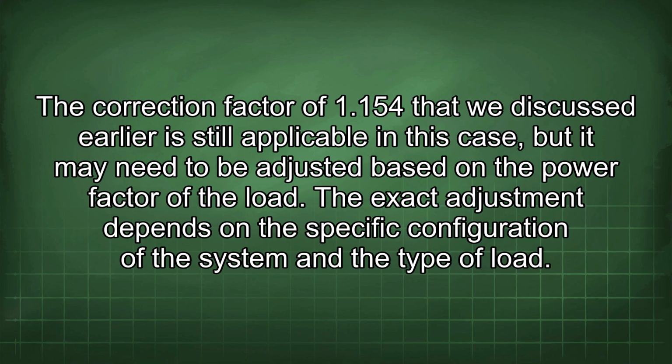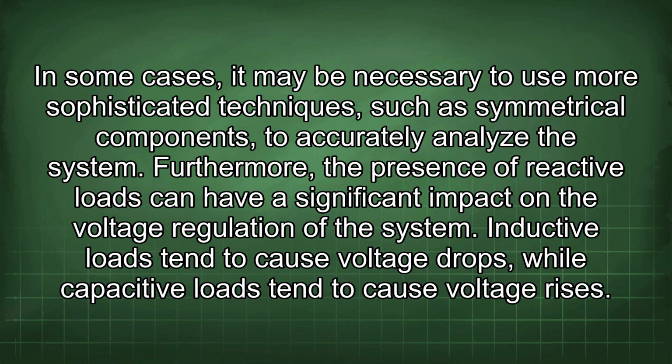The correction factor of 1.154 that we discussed earlier is still applicable in this case, but it may need to be adjusted based on the power factor of the load. The exact adjustment depends on the specific configuration of the system and the type of load. In some cases, it may be necessary to use more sophisticated techniques, such as symmetrical components, to accurately analyze the system.